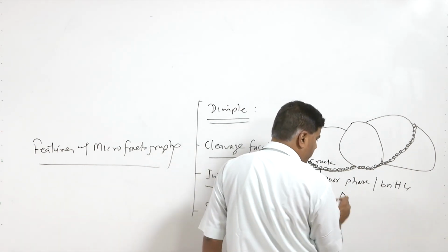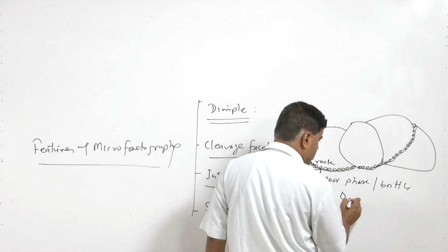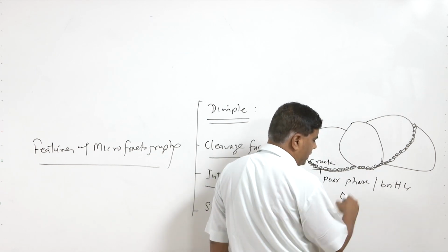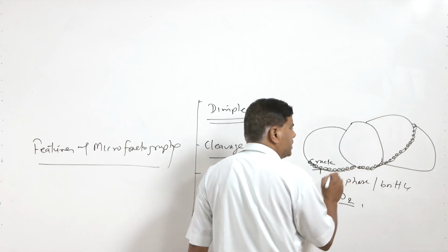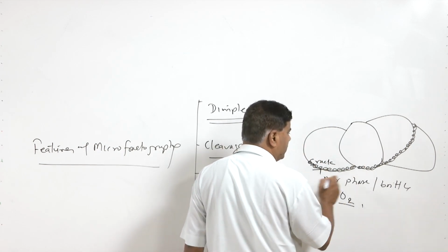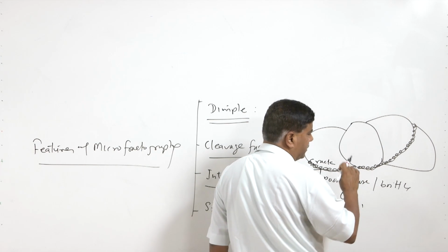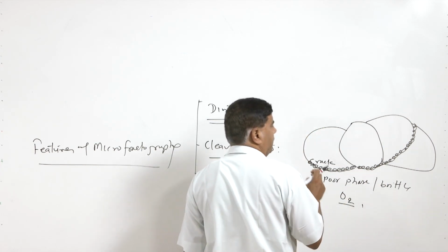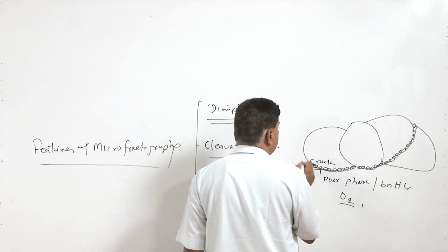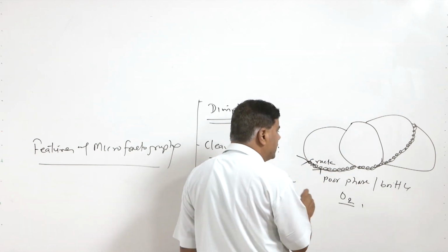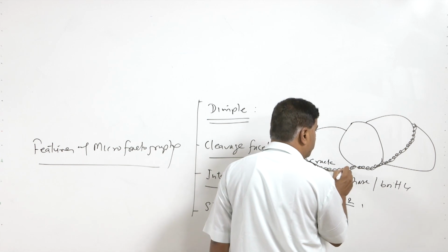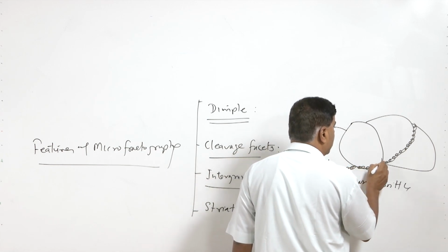Or there is precipitation of undesirable constituents like oxygen in the case of nickel alloys. These provide very low strength, low ductility zones where, under favorable conditions, if the crack has nucleated, then it will easily propagate through these grain boundaries.